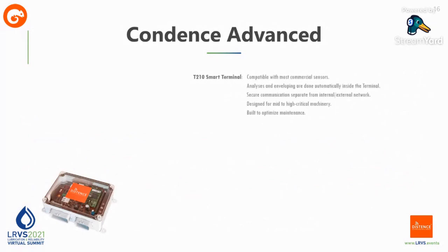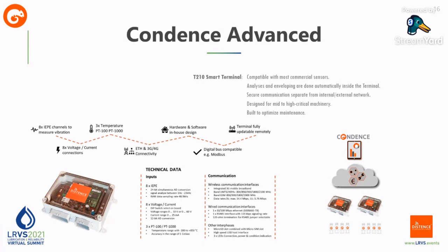We sample acceleration data at 48.9 kilohertz, 24-bit, and can adjust the sample length up to 1 minute at this frequency. Between 1 and 2 minutes, we tune down to 9.7 kilohertz for data storage's sake. And theoretically, if we combine all independent channels, we can go up to nearly 20 minutes, although we haven't seen any use case for this yet.